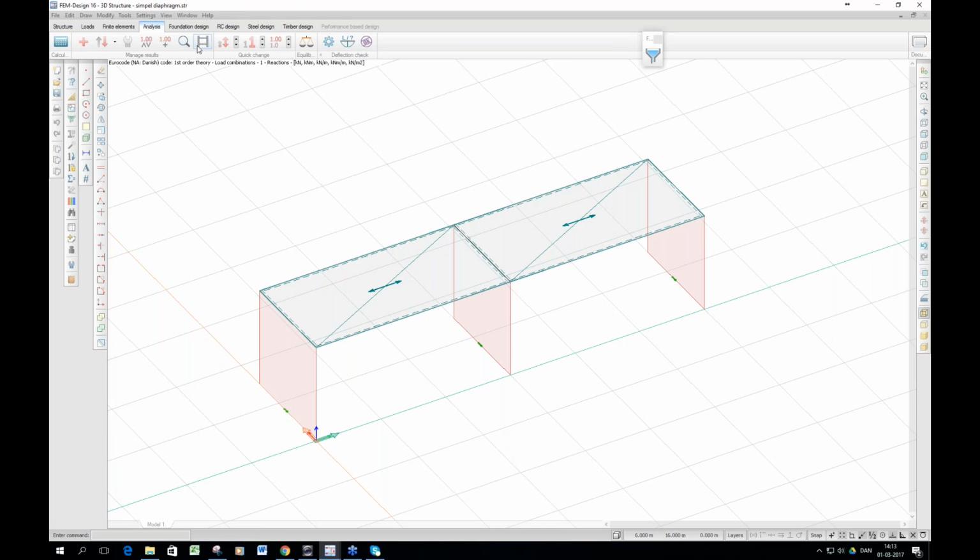and I show you the forces, they are equal. This is what, if I design this by hand, I will do it like this. Of course, you need to make sure that the slabs can distribute the load like this. So you need to reinforce around your concrete slabs, your hollow core slabs,